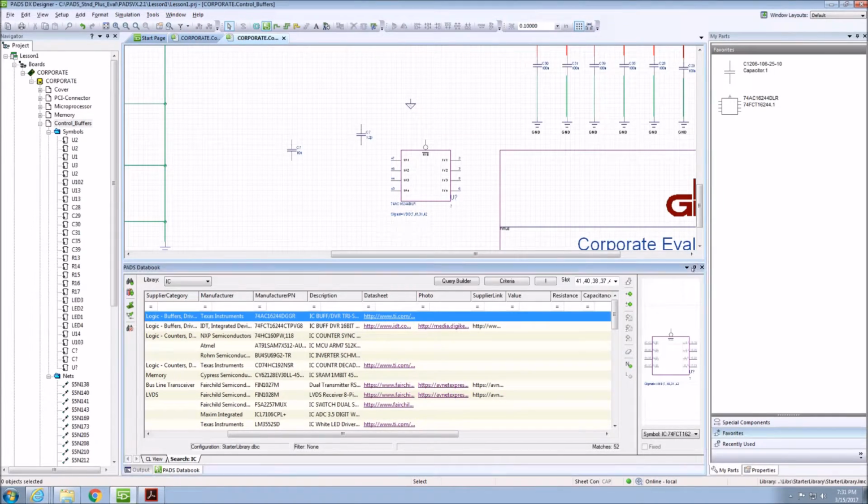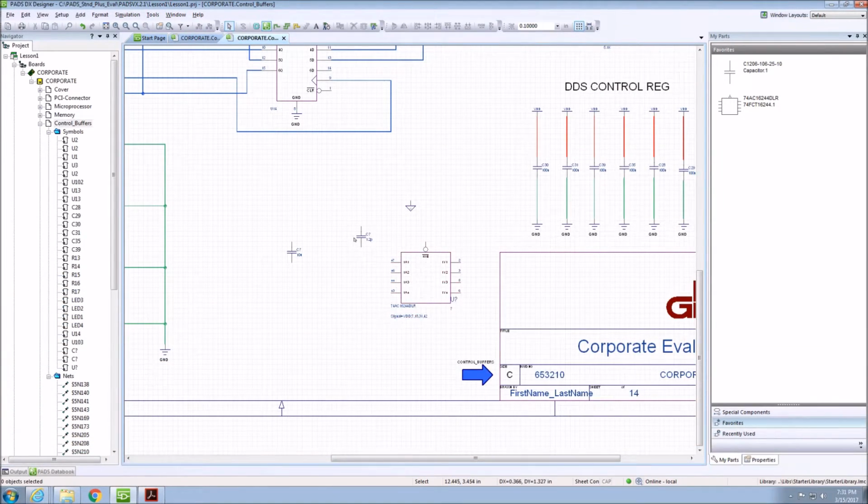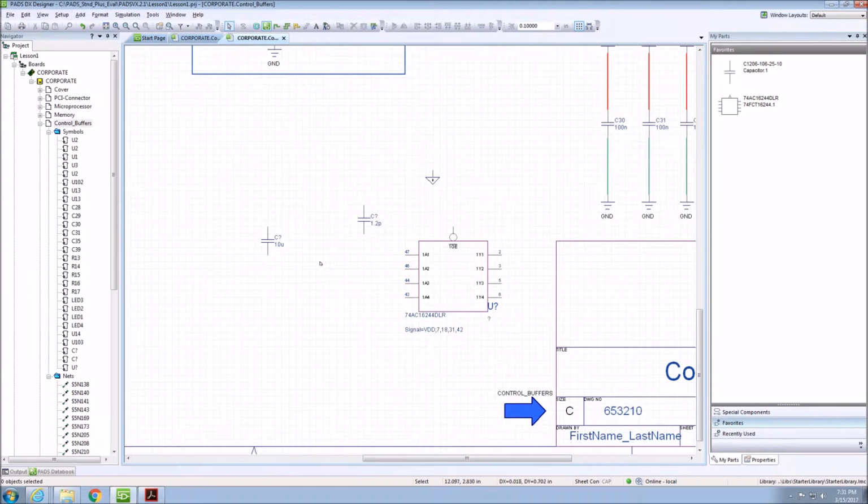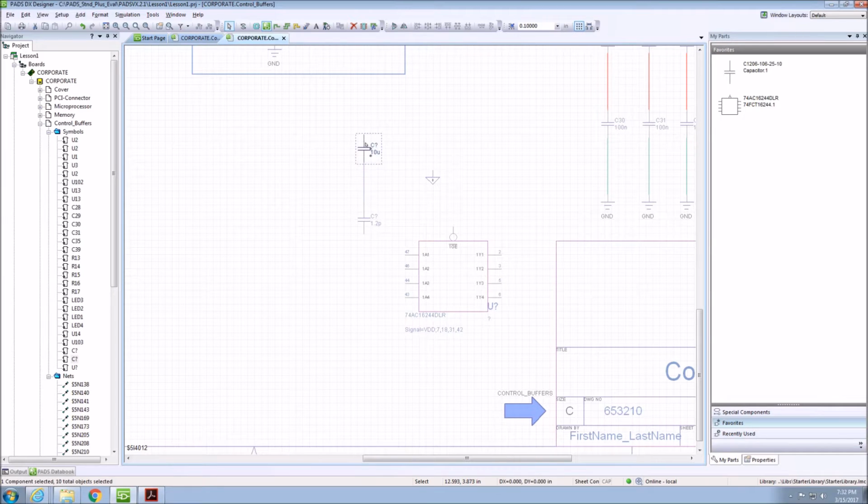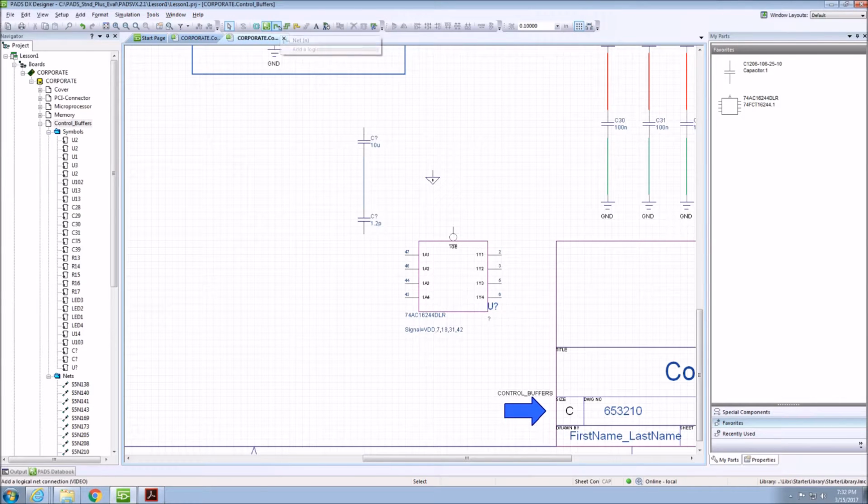Creating connectivity between components in DX Designer is very simple. The first way to achieve this is to just drag two components so two pins are connected and drag them apart. This automatically creates connectivity between the two.